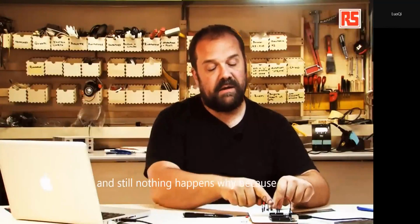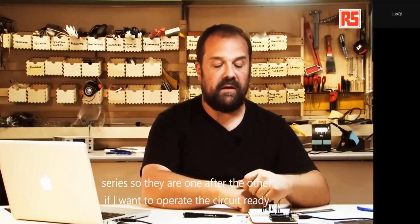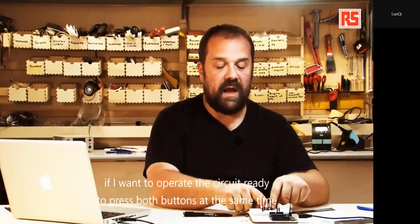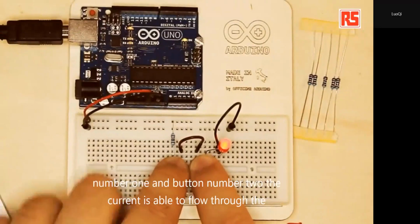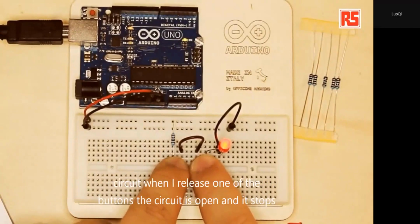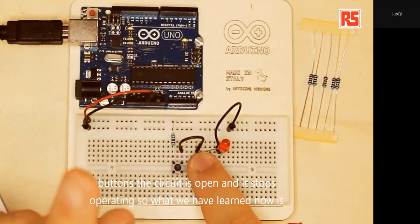Why? Because these two buttons are connected in series, so they are one after the other. If I want to operate the circuit, I need to press both buttons at the same time. So look at this. When I press button number 1 and button number 2, the current is able to flow through the circuit, and when I release one of the buttons, the circuit is open and it stops operating.